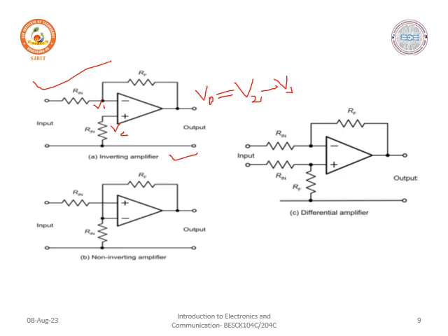Consider the non-inverting amplifier, where you apply the input to the non-inverting terminal. The plus indicates the non-inverting terminal. The inverting terminal you make ground through a resistor. So in V2 minus V1, V2 is greater and V1 is 0, so the output voltage is positive. Therefore we can consider that the output voltage in this non-inverting amplifier is in phase with the input.